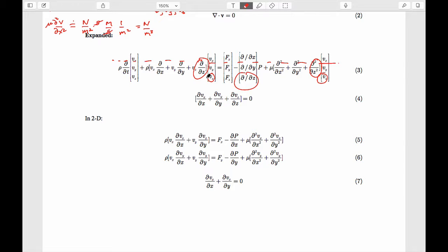So in other words, if you imagine flow within this horizontal plane, which is my thumb and my first finger, then any picture of flow within this plane will be repeated in any planes that are adjacent to it. So the gradients of velocities, or the pressure gradients as you go up in the z direction, will be uniformly 0. And so the pressure gradients here, by definition, have to be 0 on this.